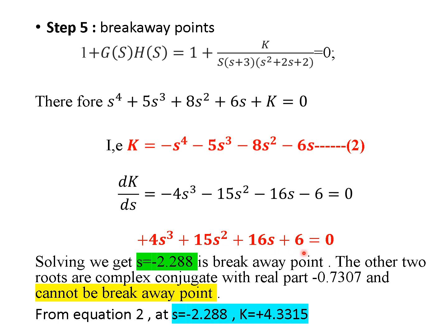Now, the equation obtained is of power cube. If it was a quadratic equation, we could easily solve this. Since it's of power cube, in the examination it is best to use the calculator in polynomial mode with the order of 3. By solving that, we get s is equal to minus 2.288 as the breakaway point.